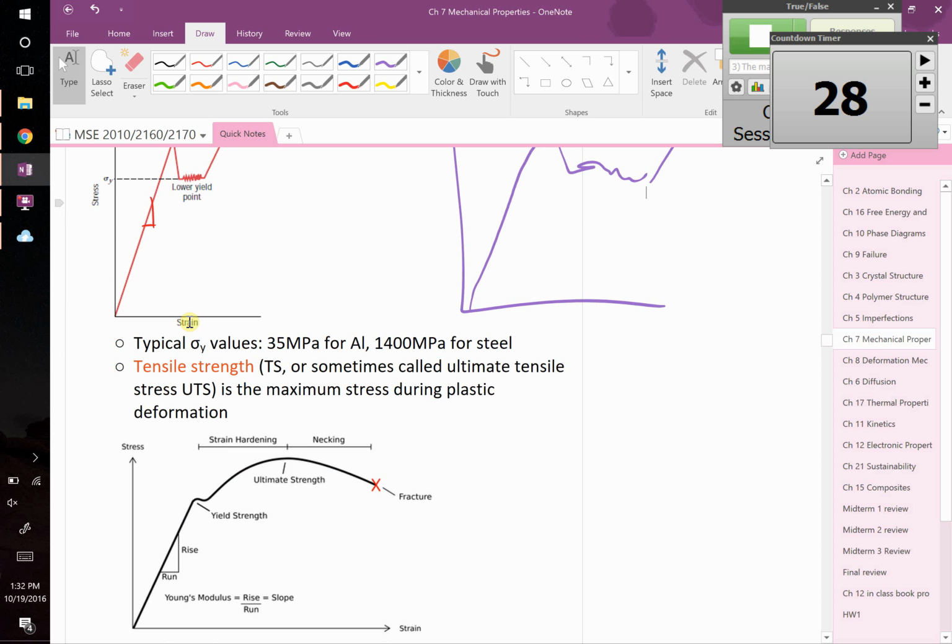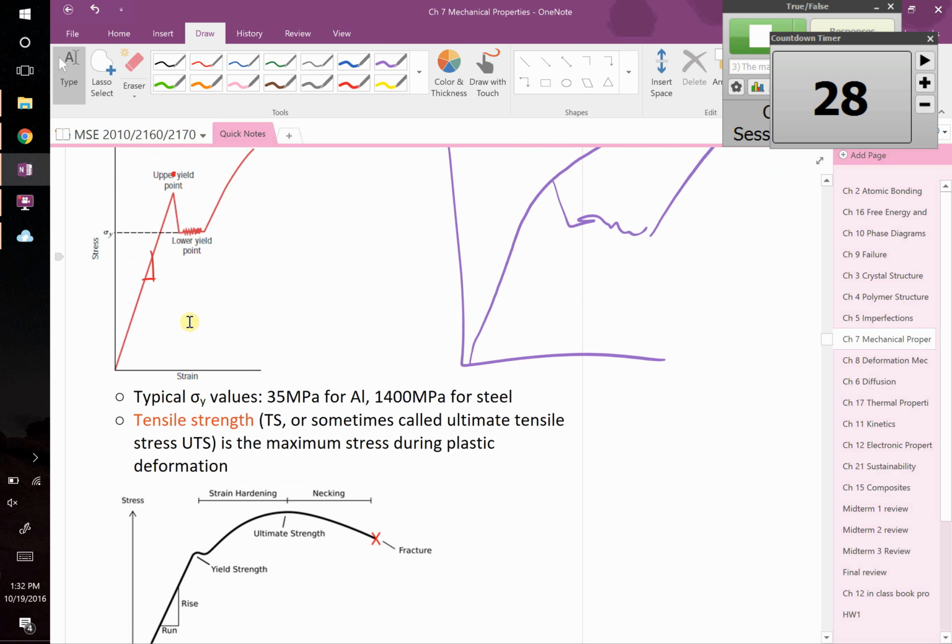Is that going to happen with our wire on the weight, that one experiment we did where it went down, went back up and down, up again? No, good question though. That one was interesting. Remember on the wire we had that we heated up, right? That thing went down because we were heating it up, and at a certain temperature went from BCC iron to FCC iron, which is a more compact structure, right? Higher atomic packing fraction. So if it compacted, the wire had to contract. So it actually went up, and then when it kept on heating, it kept on expanding. And then in reverse it happened. So that had to do with a phase change, not to do with a yield phenomenon.